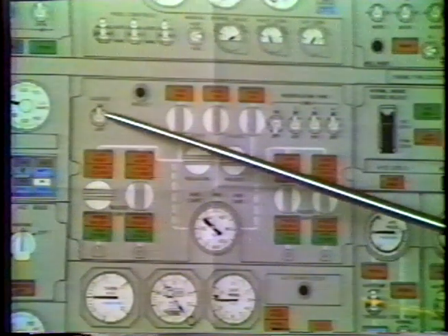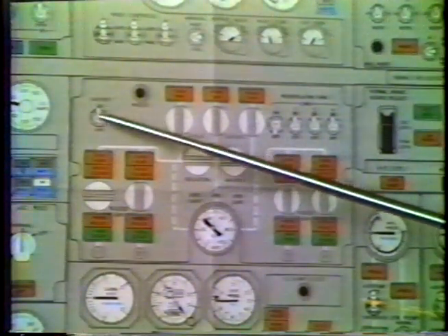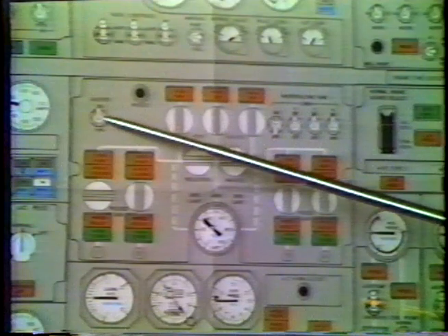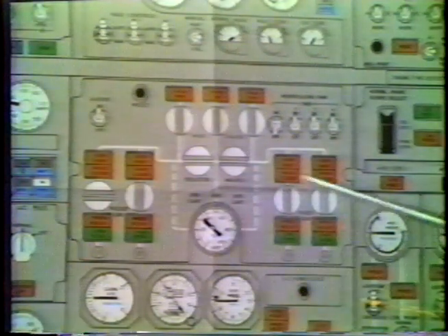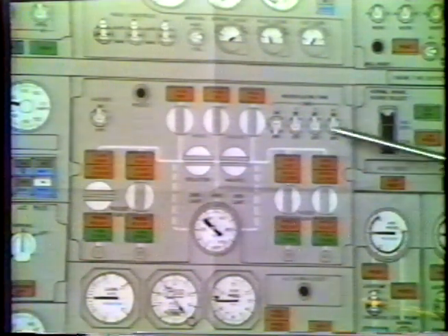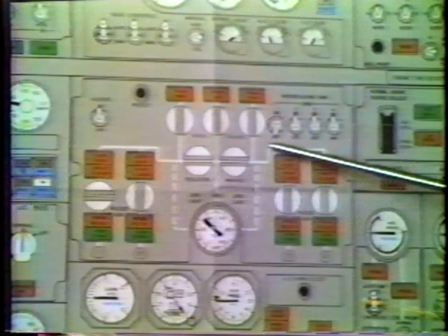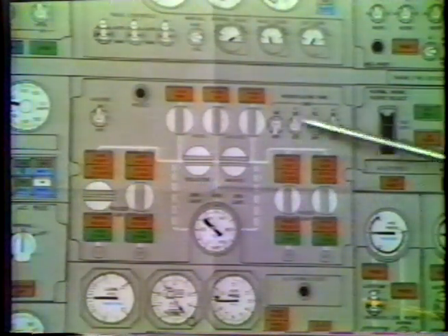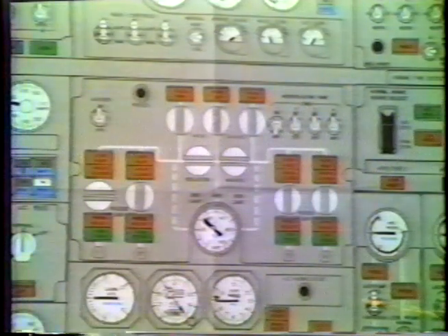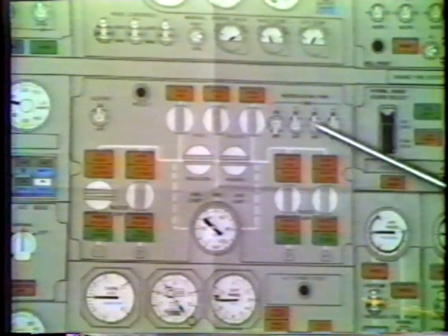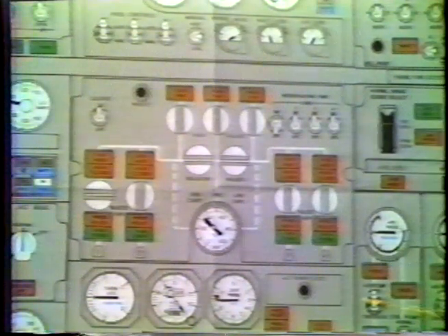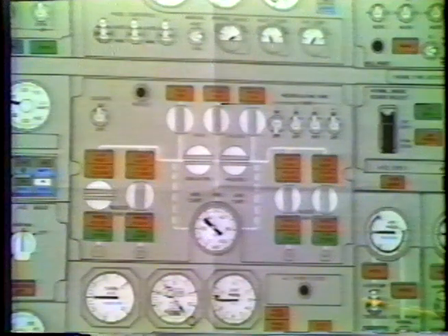The Gasper fan is for the eyeball outlet in the cockpit and in the cabin throughout the entire airplane. Recirc fans, we have 4 of them. 1 is for the cockpit, 2, 3, and 4 is for the middle, nose and tail of the aircraft, and all they do is circulate air that is in the cabin around so it doesn't stagnate.